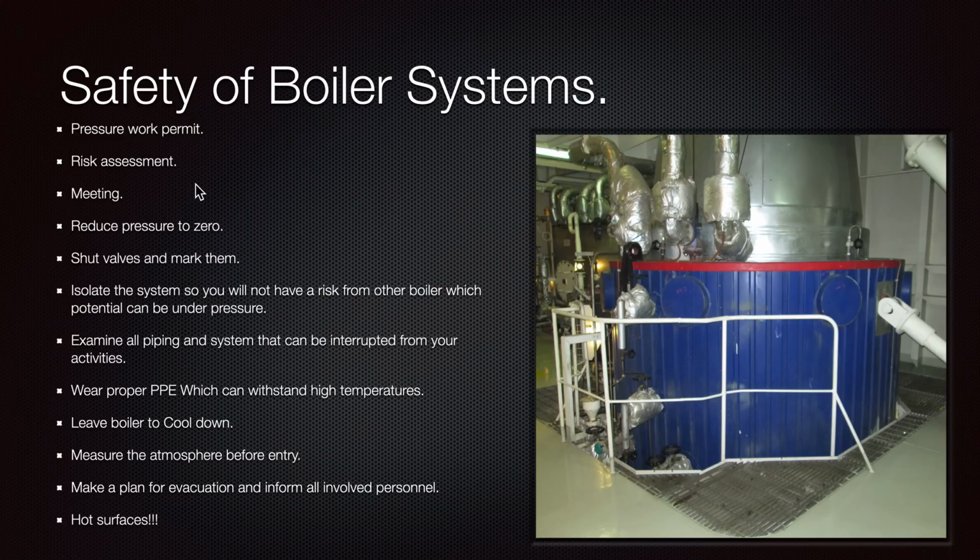So, let's say for example, if the checklist tells you that you need to check the pressure here, and you have a pressure gauge somewhere here, you have checked and there is no indication on the pressure gauge. But are you sure that your pressure gauge indicates the proper pressure, or that what you read there is proper? So you cannot rely only on one thing. And through experience, you'll be able to identify if there is any pressure inside.